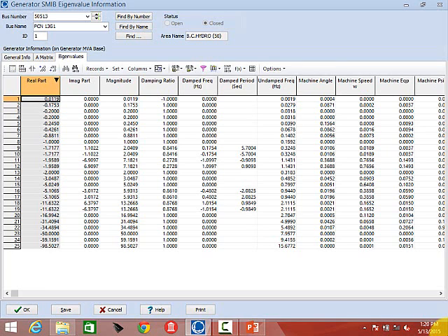We then do an analysis to try to figure out what part of the model is causing this. This is known as participation factor analysis. We're looking and saying, what is the cause of this positive eigenvalue?